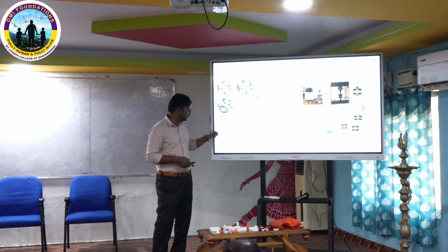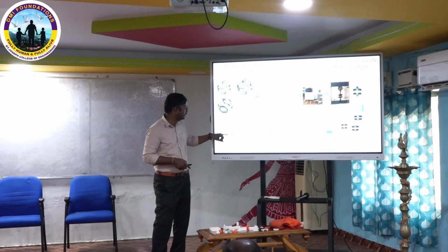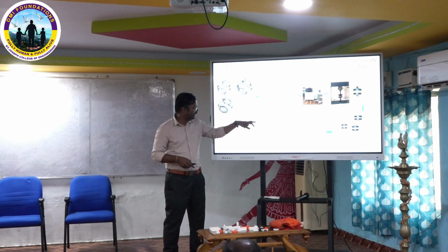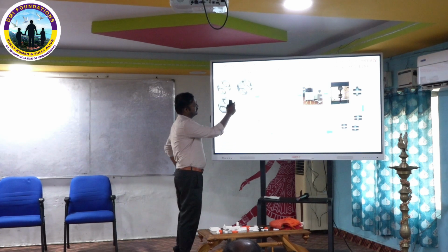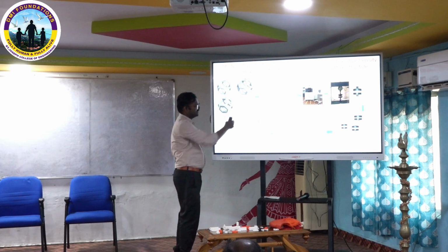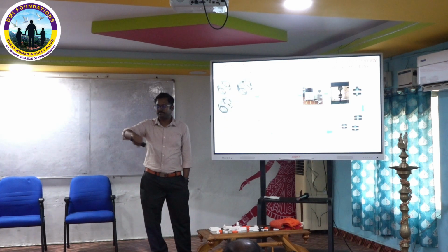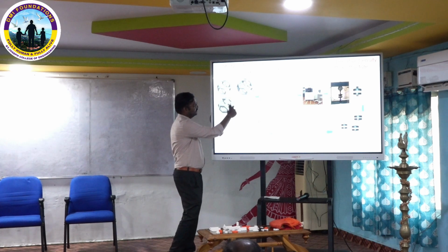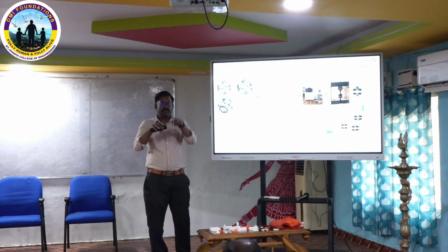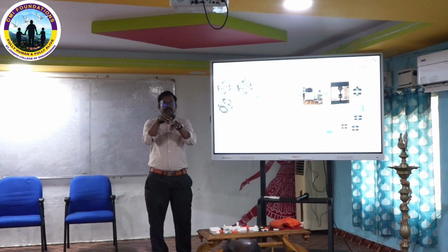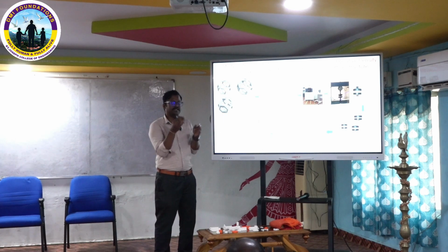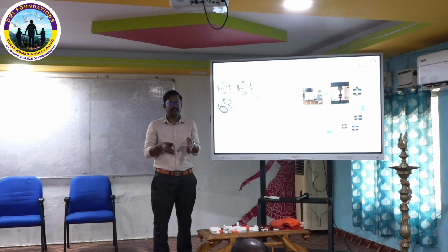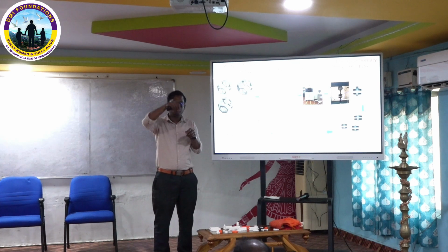Next is the hatching distance. Just think this is the first hatching, where the laser moves along a particular line. This is the first line, this is the second line, and then the first and second lines overlap. To control that overlapping, we need to finalize the distance between each hatching. That means not layer, but one movement.